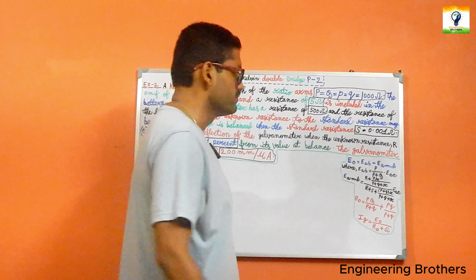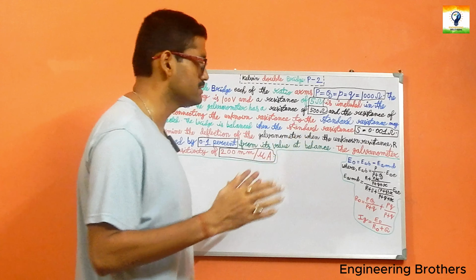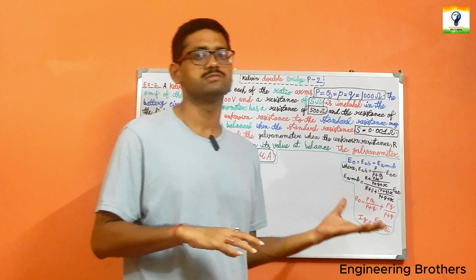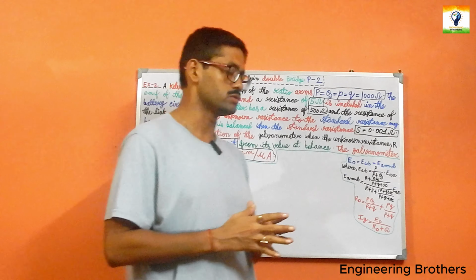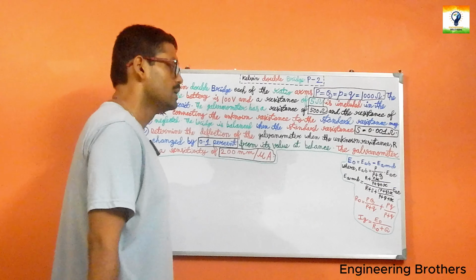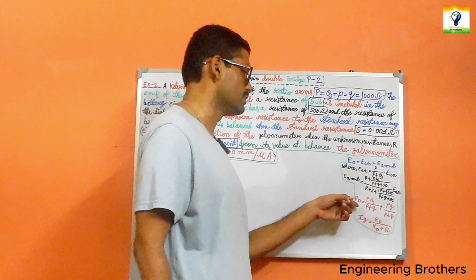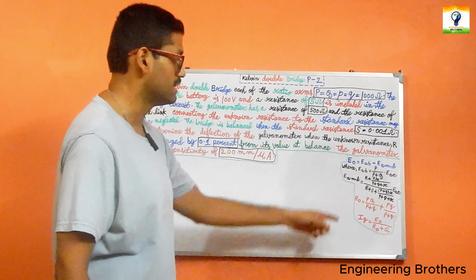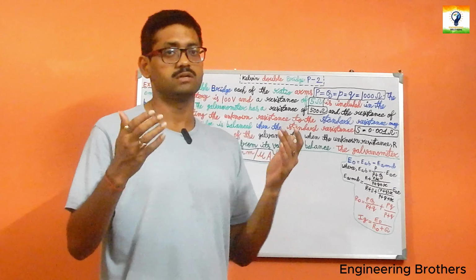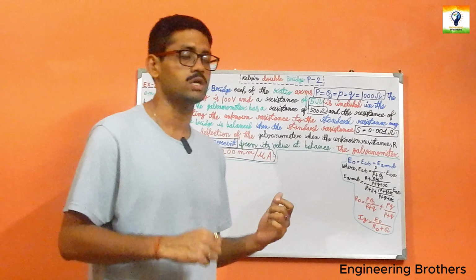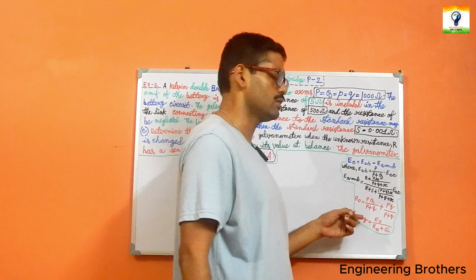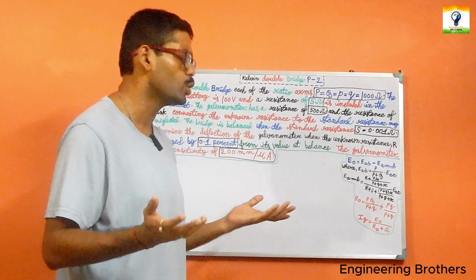So E0 is nothing but the difference of these two voltage elements. And how do we get that? I applied Thevenin's theorem. First I got the open circuit voltage, so E0 is the open circuit voltage, and in our second part we got our Thevenin's equivalent resistance, which is considered as R0. After concentrating on our Thevenin's equivalent circuit, we got the galvanometer current, or load current.